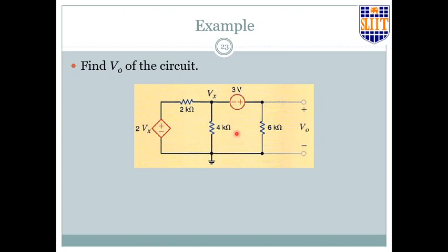Those techniques will be taught to you in the second year, right? So for now, if you have a dependent source and you want to perform mesh analysis and nodal analysis, this is how you do it. Simply treat them as independent sources when you apply KVL equations, and then substitute a value for the dependency, that is in this case Vx, from other means, and then you will be able to simplify the system.